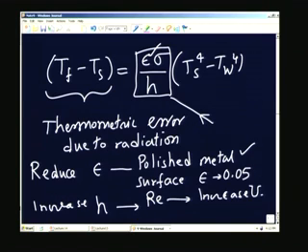In fact, if you remember, in lecture number 13, I indicated that u can be increased by having some kind of an arrangement in which the fluid is accelerated and flows past the sensor at a higher velocity than it would otherwise. You could have some kind of a small converging diverging nozzle, and the sensor can be within that,